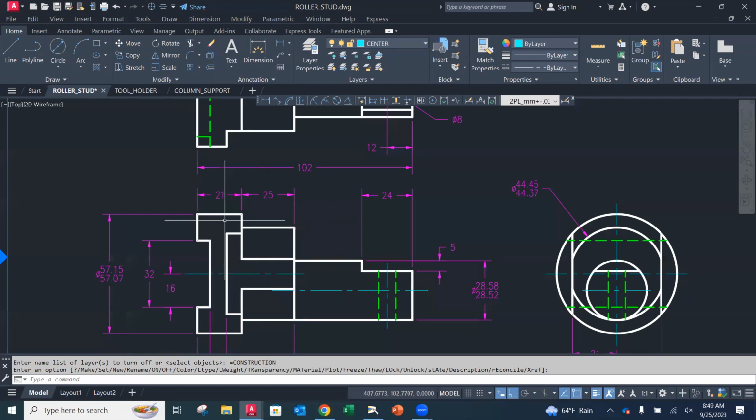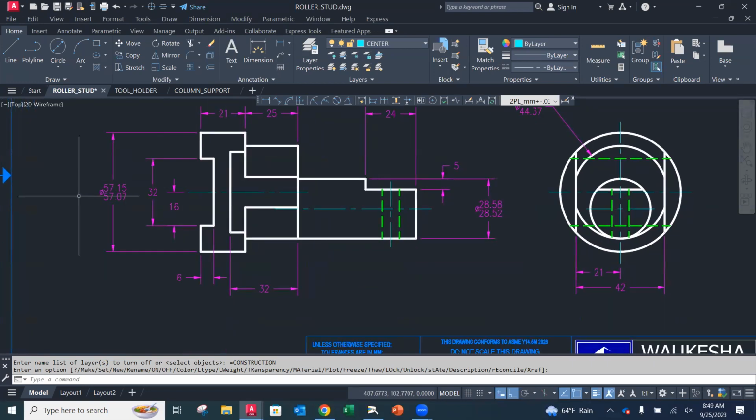Now, you'll notice that this is like an outside diameter. So the best place to place this diameter is where we see it in what I call its rectangular view. You'll notice that I placed it over here. Putting it over here isn't quite as clear. The standard is we want to put it in its cylindrical view, especially when it's an outside diameter like this. Because it's going to be put in as a linear dimension instead of a diameter, we're going to have to put the diameter symbol in front of that limit dimension.